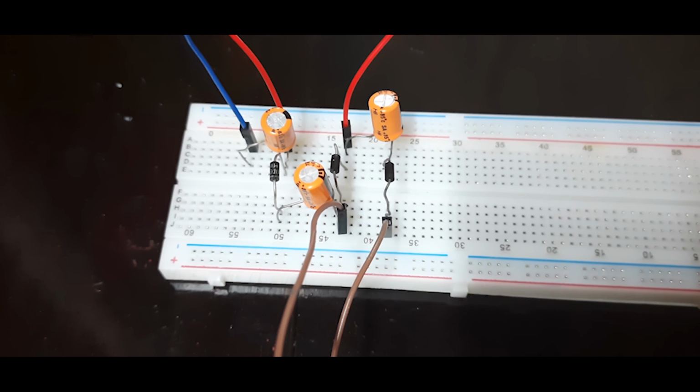So before changing the input, make sure that you switch off the input and do this discharging of the capacitor and then charge it to the desired value again. Then only you will get the correct output value. So please note this point and repeat this experiment for various input voltages. Thank you.